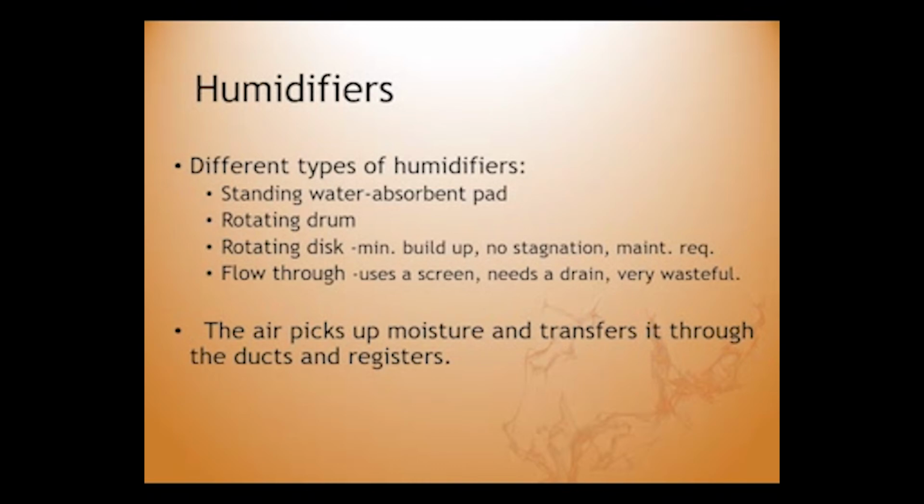Humidity is the amount of moisture air can hold at any given temperature, and as we discussed in Module 203A, humidity in the air is a large part of our human comfort level. Less than 20% it feels cold because we have lots of skin evaporation. However, more than 80% feels muggy because it prevents any evaporation from our body. About 40% at around 22 degrees feels right to most people.